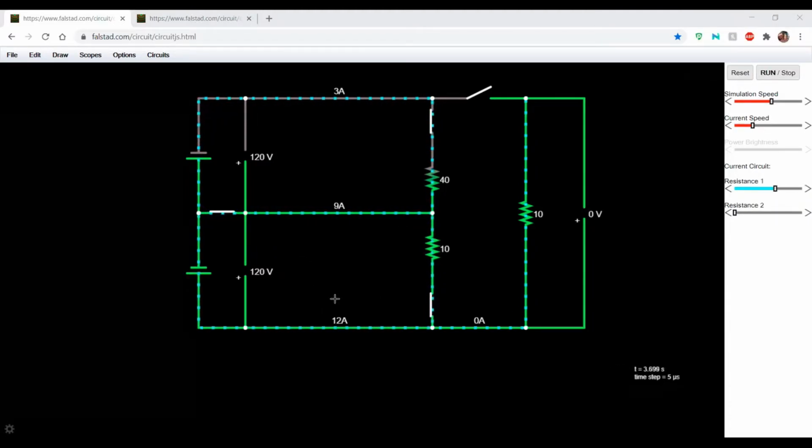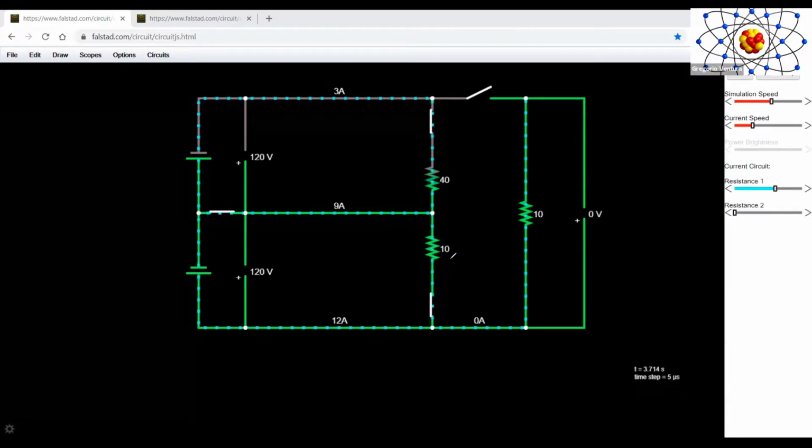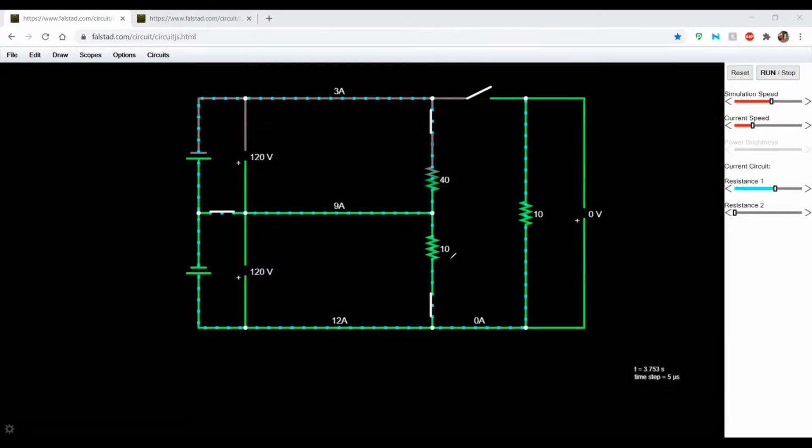Okay, so the current is coming from the neutral there then? Yeah, that's how it's flowing. So it flows both ways along the neutral? Yeah, it's got to be flowing either way, depending on the amount of load that you have in the circuit. Okay, thanks. You're welcome. And that's why it's not called a neutral. That's why it's called the identified conductor.